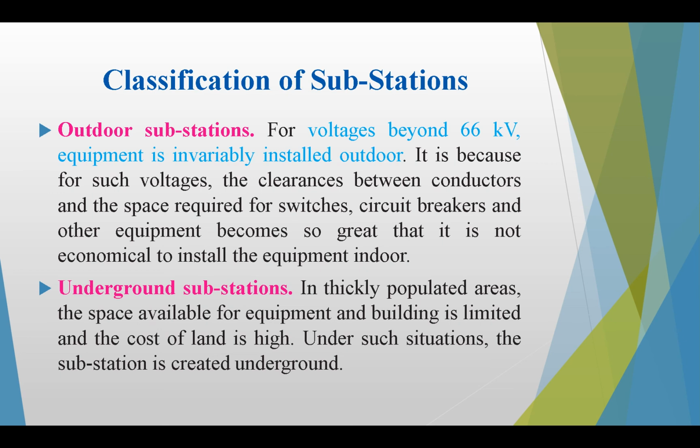It is because at such a voltage the clearances between the conductors and the space required for switches, circuit breakers and other equipment become so great that it is not economical to install the equipment indoors, because it requires more cost and high space, so definitely we need to invest more.